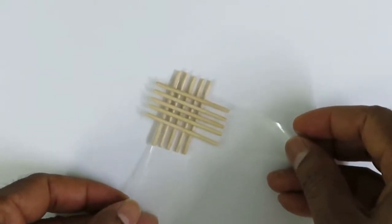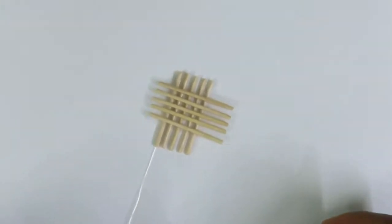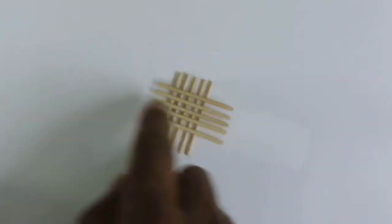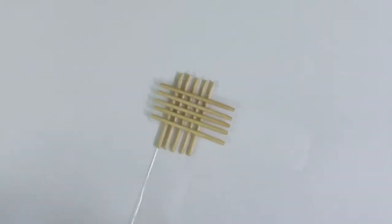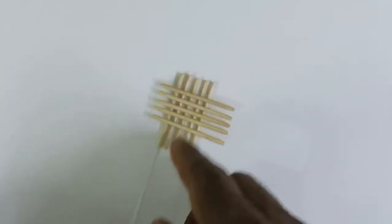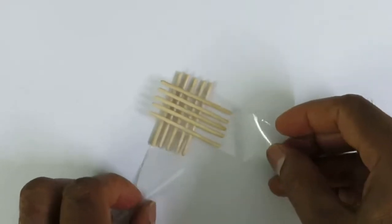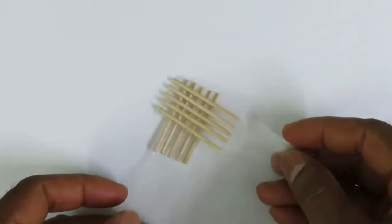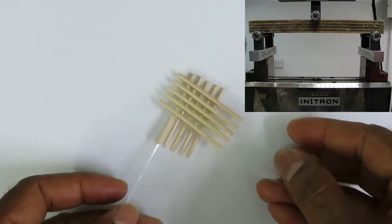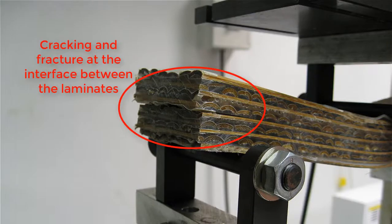The most common is the 90 degree cross ply, so that the mechanical properties of this composite in this direction and in this direction will be more or less the same. So it gives isotropic properties in one plane of the laminate. But between the laminates there will be some weakness, because such composites will fail by fracture between the laminates. So the cracks will initiate at the interface between two laminates.